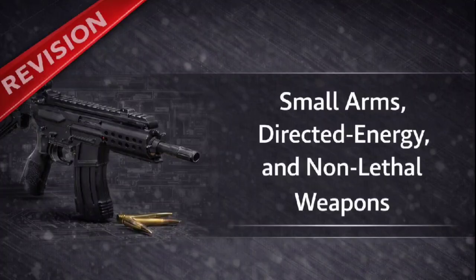When does the system actually break that lock? After that initial, short rearward travel, the barrel is mechanically stopped. The breech block, however, unlocks and continues moving backward using its stored momentum. And that separation allows the rest of the cycle to happen. Exactly. That separation lets the block perform the rest of the operating cycle, extraction, ejection, cocking, before the spring returns it forward to load a new round and relock. The positive lock during peak pressure is what makes this system vastly safer and more capable of handling powerful rifle and machine gun cartridges. Now, recoil systems are subcategorized by the distance that lock unit travels together.